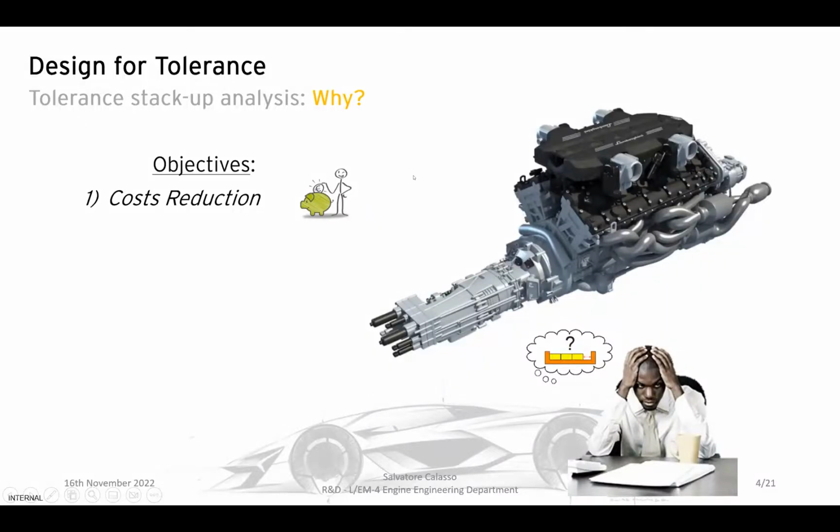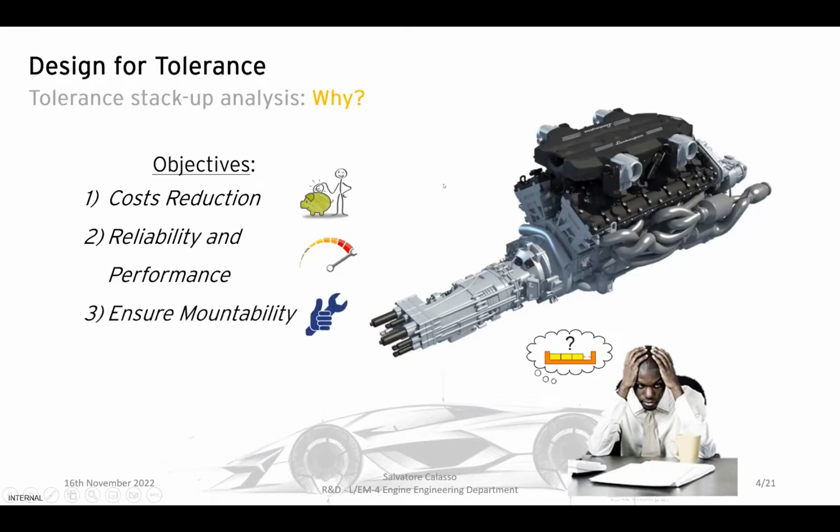So the reason to perform a tolerance analysis could be cost reduction, to get the right reliability and performance of the part, but also to ensure the mountability of them.